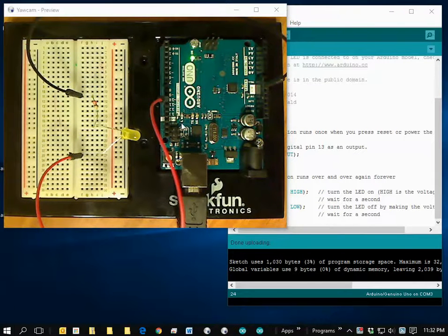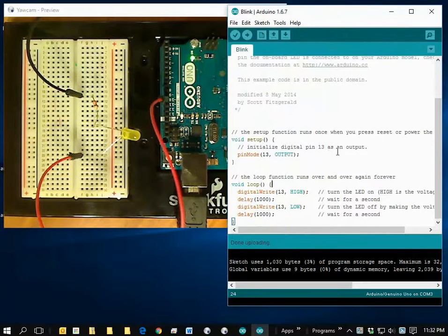Okay, so I'm back, and all I really did was change the red wire here from being connected to pin 13 over to pin 10. You can see the program is still running. As long as I have it powered up here, it's going to run the last program that was uploaded to it, but the LED is not blinking. That's because I need to make some changes to the program. Now this right here is a comment line, so it's not really going to do me any good to change this one, but I'm going to go ahead and do it just for commenting purposes.